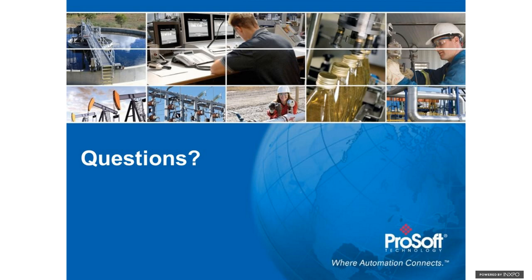All right, and next question just came in. What are the main reasons to use radiating cables versus regular omni antennas, and when are radiating cables not a good solution? Good. Radiating cable offers a lot of benefits when equipment follows a predetermined path.